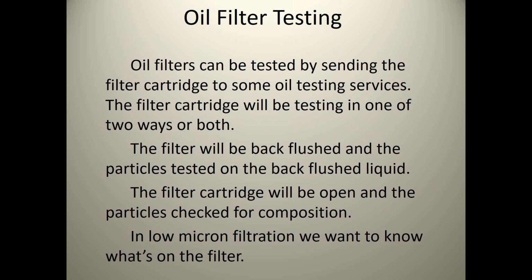The guys at my plant made a little tool with a cutting wheel off of a pipe threading machine, and we actually cut the filter open, took it off, and then ran a magnet up and down the filter to see how many iron particles were on there and what they look like. Sometimes we would scrape the stuff off and look at it under our microscope.